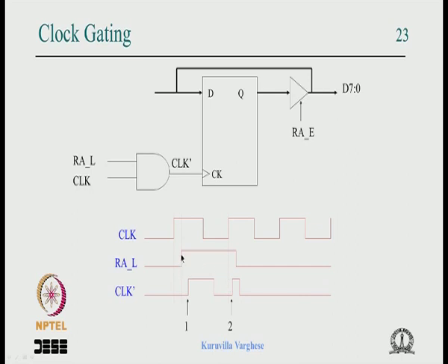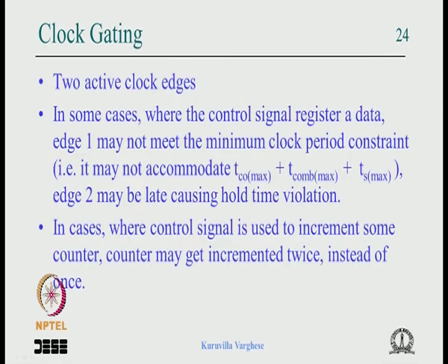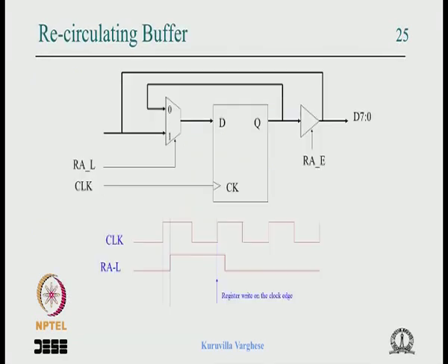If we can resynchronize this latch signal with a negative clock edge, then it comes like this, and you can AND it with the resynchronized latch signal. The clock is ANDed with the resynchronized latch signal, then you will get a pulse correctly like this, and you can use it to clock this particular thing. So I have explained the idea behind it, and that is what I am going to show now.